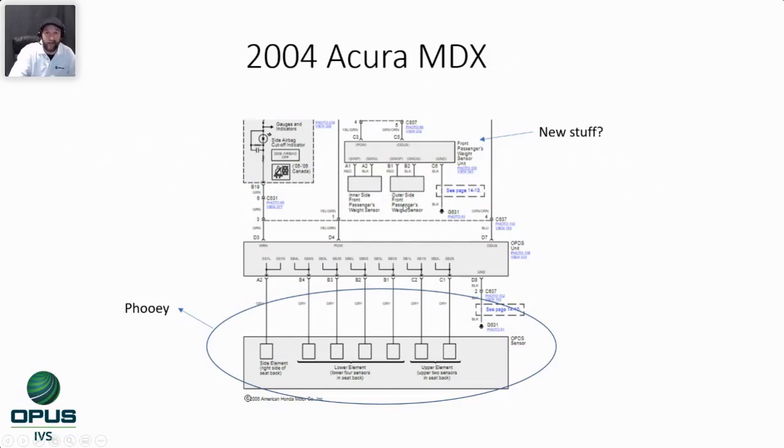That to me sounds like a strain gauge. I can go in there and do a test and look for voltage. Do I care what that voltage is? No, what I care about is, are they the same, right? We have an inner and an outer on this one. Are they the same? If both are at 0, that's great, right? That means we have nothing at all applied. If they're both at 2 volts, that means we have nothing applied. It doesn't mean it's good. What it means is we have something that we can check.